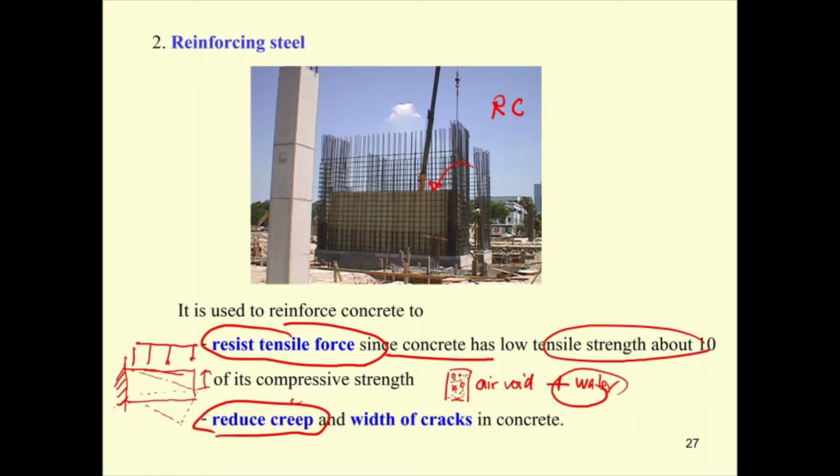One thing is you have to put the steel into this portion in the proper amount. The steel will help the concrete take care of the leaching out of the water, and the creep can be reduced. The same goes for reducing the width of cracks. We also have temperature steel, because temperature change of the slab produces cracks.